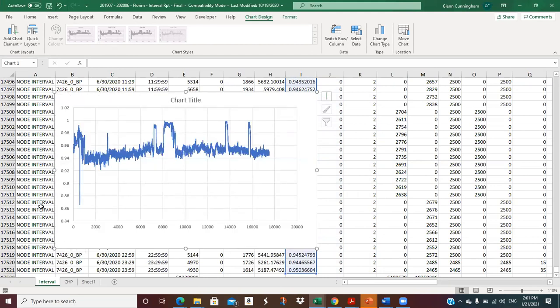Okay, so you see, this is what you see. I think these guys had some power factor correction going on because this is pretty good. There's not much of a project here because they're pretty big. I mean, they're 5, 6, 7 megawatts. So it's a good size. They make porcelain tile. So it's a big plant up in Clarksville. But you see, what's their low? I don't know what their one little dip is, but beyond that, it looks like they're hitting 0.92 or something like that. That's not too bad.